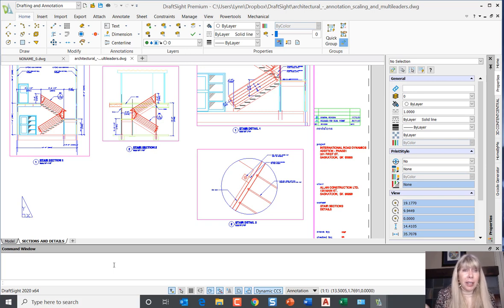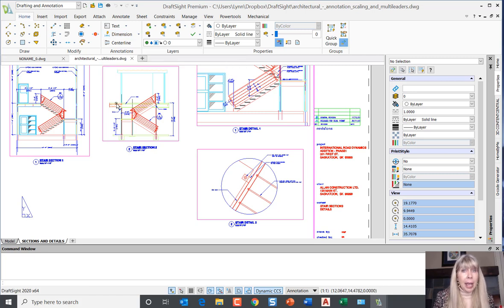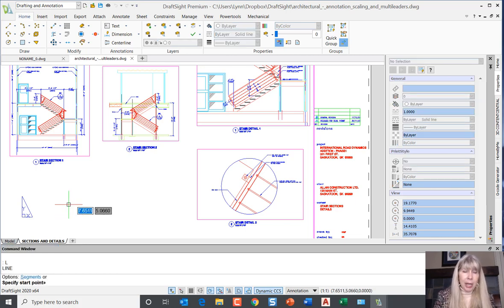So what's it feel like? I want to execute commands. Of course, you can execute them from the ribbon, and some of the things are not in the location you're used to with AutoCAD, so it will take you some time to relearn that. I'm not going to lie. Or if you like to type and you know the commands by heart, you can type them in as well, exactly the same way you would inside of AutoCAD. Then I'm drawing a line. Or I can draw a circle, C for circle, no surprise. Very easy, very low stress, right?